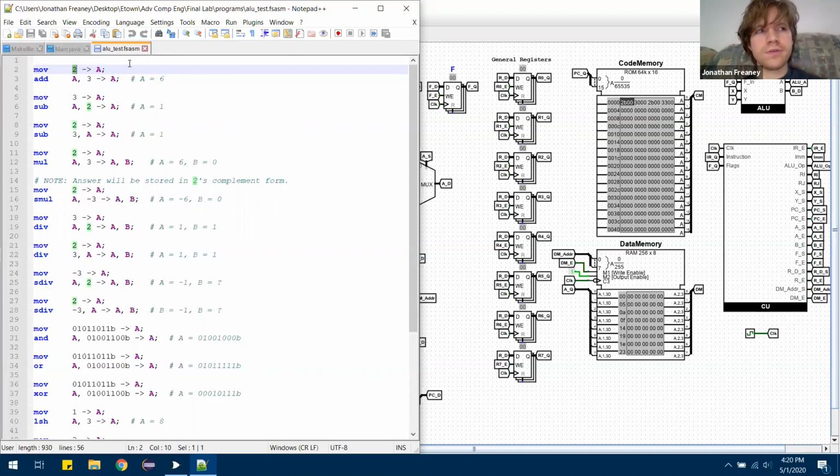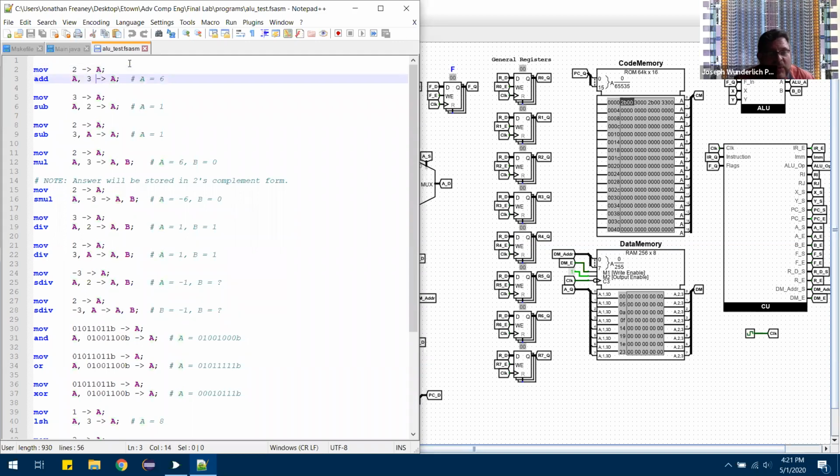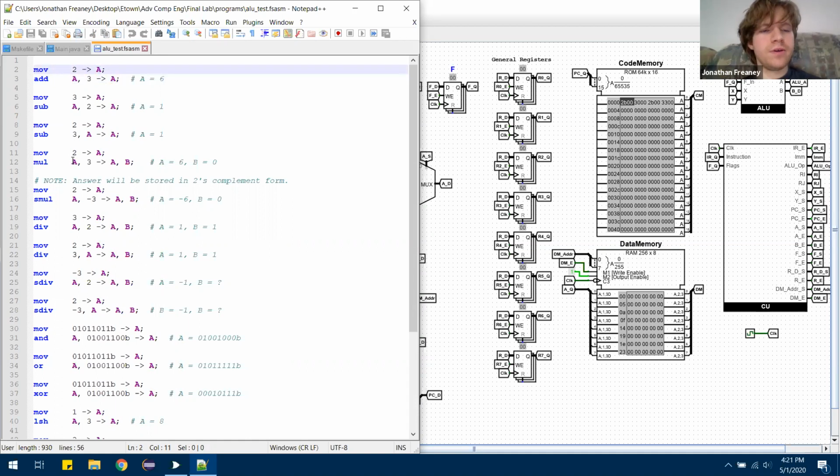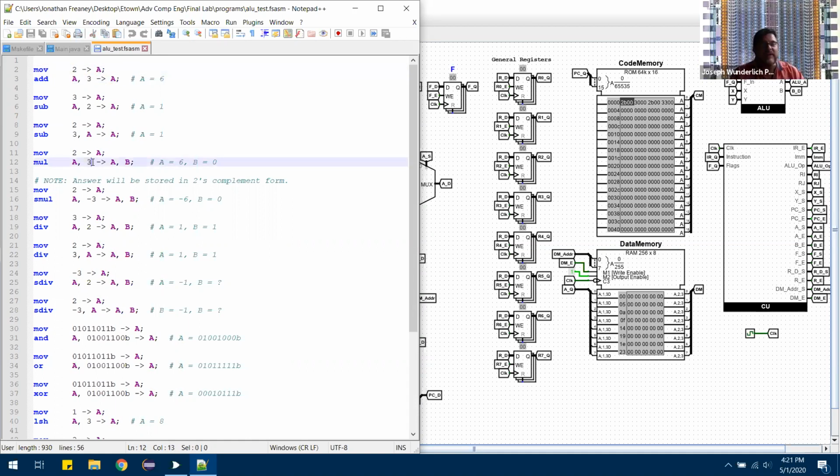So you have an immediate value here, and then that's being moved into the accumulator. I like the multiply because you can see that you're using the A and B there. You have A and A and 3 in this case, so they're added together, and then they're put into A and B. You hardly even need register transfer notation at all when your code makes sense in your syntax. This was a huge improvement for testing the machine. I'm surprised more assemblers don't look like that.